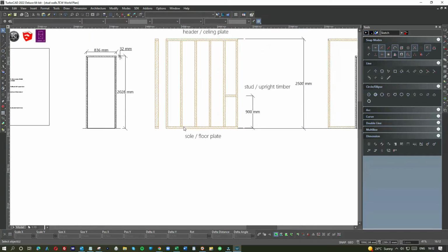Right, so as you can see, first of all you put the plate in, and then what you do is you actually put the bottom plate and the top plate in, and then pop the timbers in, so that you always have a flat plate on the ceiling and a flat plate on the floor. That's to spread the weight. It couldn't be any other way, otherwise the boards would go up through the ceiling or down through the floorboards.